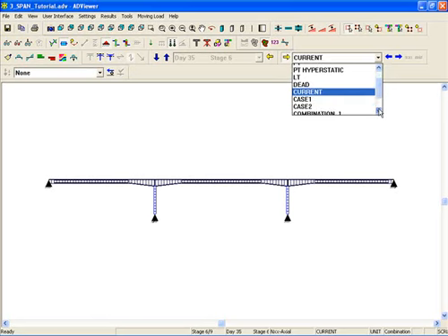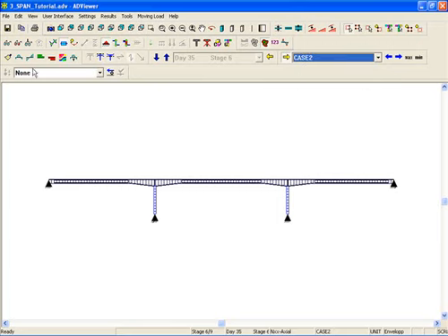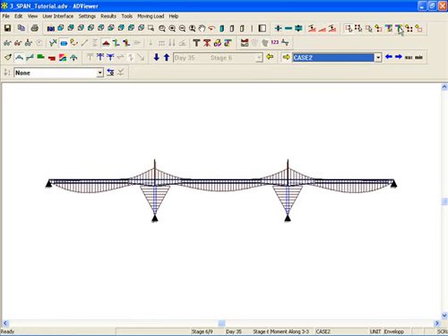If we continue to scroll down, we also have the moving load cases that were generated by the user, case 1 and case 2, also the two combinations, including the envelope, and the program-generated moving envelope, which is the envelope for both of the moving load cases. We can select any of these cases or combinations. We'll select case 2, and again, any of the different results can be viewed on screen. We can toggle the composite for each of these cases or combinations.